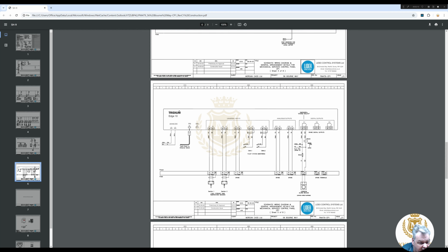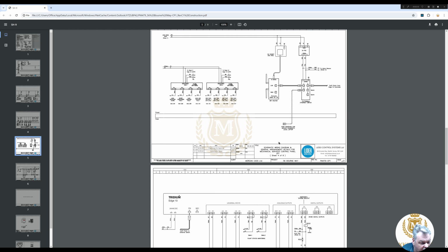and on the Edge 10 we've got temperature sensors, section 1 and section 2 of the cold water storage tank. Apparently we've got an output for a corridor alarm beacon, lots of spares there, so it looks like we're monitoring CHW and then the DIM 1 and DIM 2 units, which is all to do with detection, leak detection, water conditioner, booster, low level for the tank and high level for the tank.